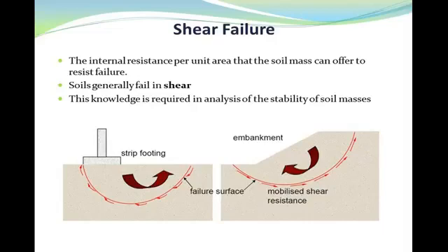Okay, what is the shear strength of the soil? Shear strength is defined as the internal resistance per unit area that the soil mass can offer to resist failure and sliding along any plane inside it. In fact, various studies showed that soils generally fail in shear under different combinations of stresses.